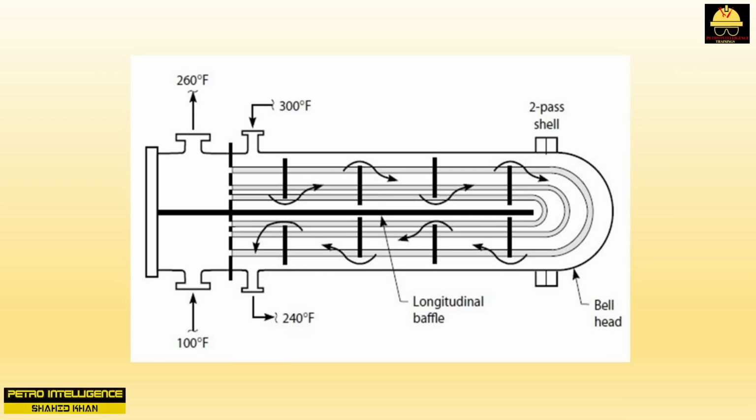Such an exchanger is truly countercurrent. The engineer does not apply the F-factor derating coefficient to the log mean temperature driving force, as would normally be used for non-true countercurrent flow. This would make it seem that the 2-pass shell configuration is inherently more efficient than the ordinary single-pass shell exchanger. And it is, in theory. Then why do we see so few of these exchangers in service?